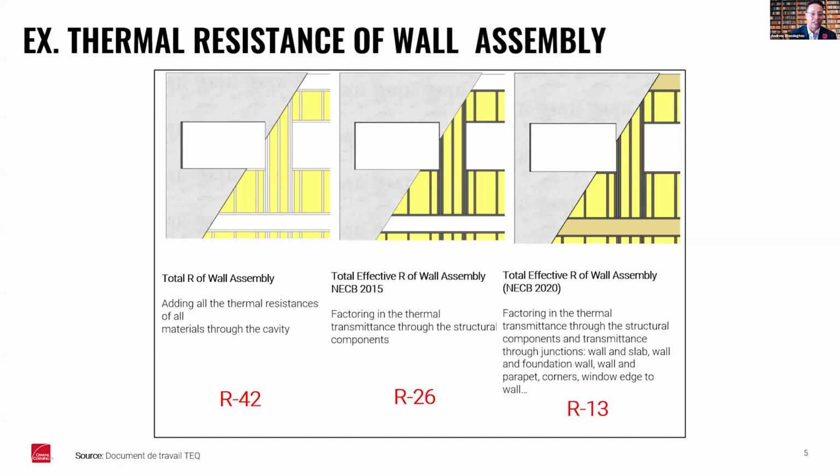So we saw the insulation value for the wall, or the amount that is actually showing, cut almost in half to R26, because we started to take into consideration the studs. The studs are not R22; they're probably R6 or even less if it's steel. Then we also have the NECB 2020, which just came into effect, and most provinces have already adopted this as well.